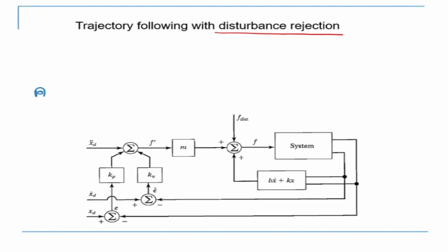Now we look at this serial arm manipulator. I have drawn it many times, and we said that velocities propagate in this direction, theta dot propagates, and forces propagate in that direction. Because of this propagation of velocity and acceleration in the forward direction and forces in the backward direction, each link affects the motion of the other link, which means this is a coupled system.